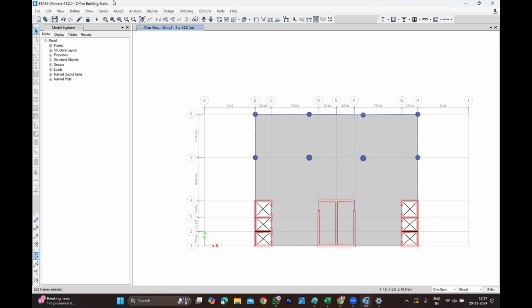If my beam depth is 500, then my column has a lesser height. If it is a flat slab, then the column height is calculated from the soffit of the slab to the top of the slab. So don't have the misunderstanding that braced or unbraced depends only on beams. If there is no stiffness connecting the column, then it is unbraced. The slab also gives diaphragm action, providing stiffness.